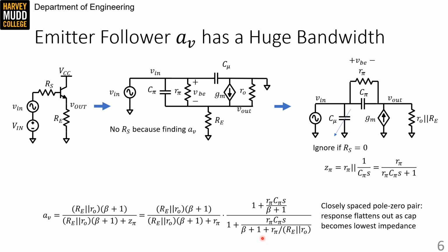So those closely spaced poles and zeros represent the CPi becoming small enough that our gain goes from slightly less than 1 as the amplifier copies a voltage from the input to the output, to the gain becoming exactly 1 as all our current flows through CPi, and our VBE value drops to 0. So that means that our gain looks flat for many frequencies and then increases slightly.